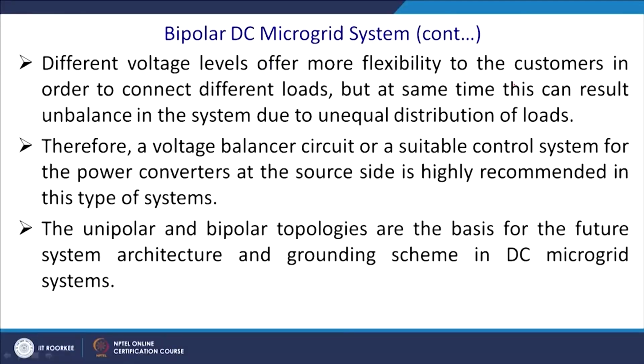Now, the different voltage levels offer more flexibility to the customer in order to connect different loads, but at the same time this can result in unbalance in the system. That is what I was saying, that this is a DC unbalance, you might not be aware of it. So, we had talked about the AC unbalance. In one phase you have more load, in another phase you have less load, but here you have this problem. Let us see how we can address it, but at the same time